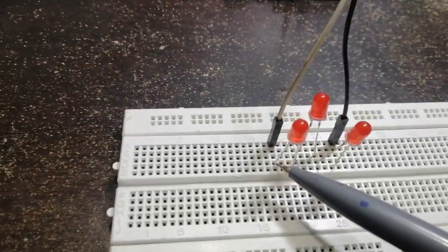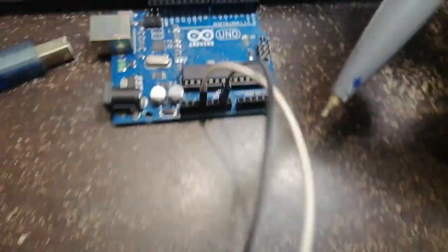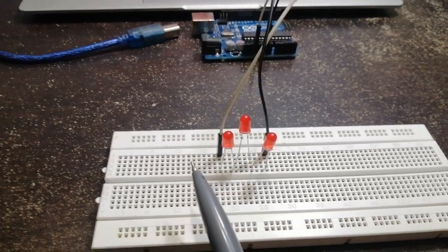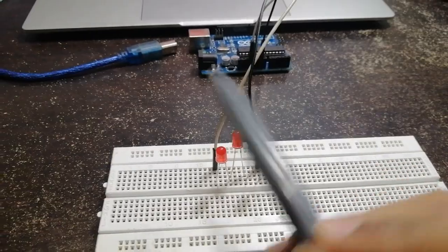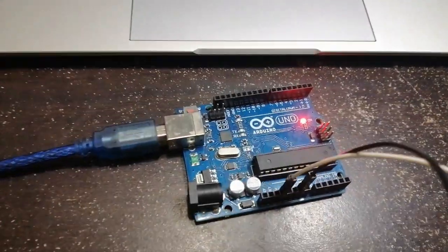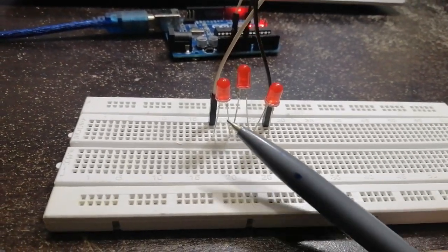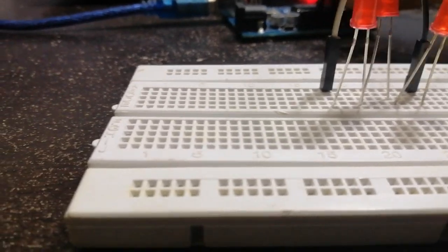So I put in the positive to the 3.3 volts in the Arduino and the ground to the ground. So this would be a series circuit, as the current would flow like this into this LED, to this one, to this one, to the ground, and back again. So I'll just plug it in and we'll see how it looks. So I plugged it in and the light is on, but it's not glowing very brightly. That's because the voltage is being distributed among these three LEDs. That's why you can't see it, but it's actually glowing really brightly.